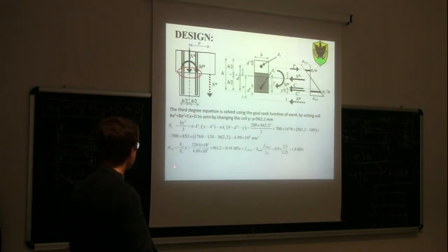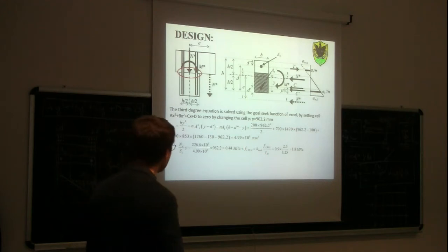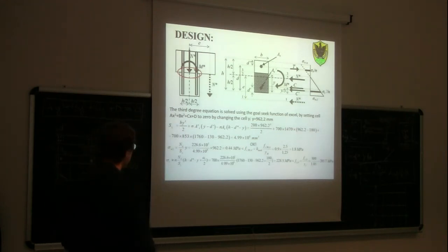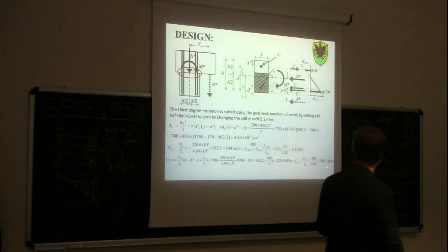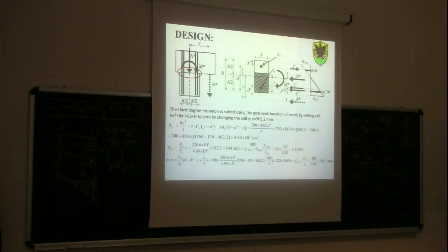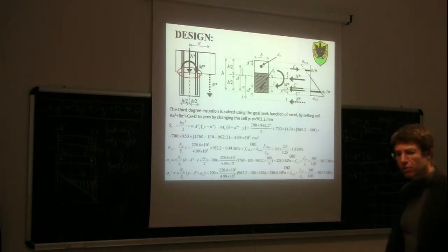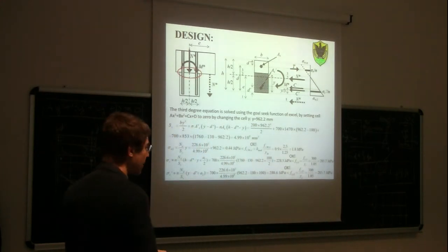Stress in the wood is almost the same as before. The tensile stress in the tension rod, as you can see, is slightly higher than before, 180, now this time is 128, it is smaller than the actual capacity, 285.7. And also the strength demand on the compressed rods is less than the strength capacity. So we could say that yes, it was possible to have a better design by reducing the number of tensile rods from 6 to 4.